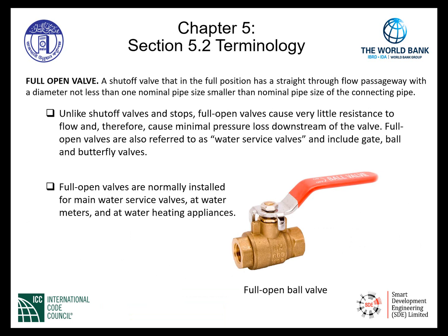A full open valve is a shutoff valve that in the full open position has a straight through flow passageway with a diameter not less than one nominal pipe size smaller than the nominal pipe size of the connecting pipe.